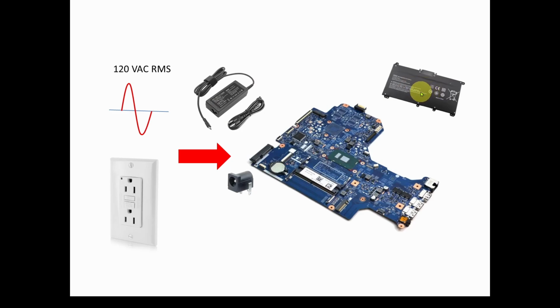And we're also going to talk about a very interesting and very common circuit that turns out is used for basically all of these circuits that take the 19 volts and drop it down to the 1 volt or 5 volts or 3 volts or whatever we need for these components on the motherboard. It's basically one circuit that's reused in all these different situations. So it's really interesting. If you understand how this circuit works, you can understand a lot of what's going on in the motherboard.